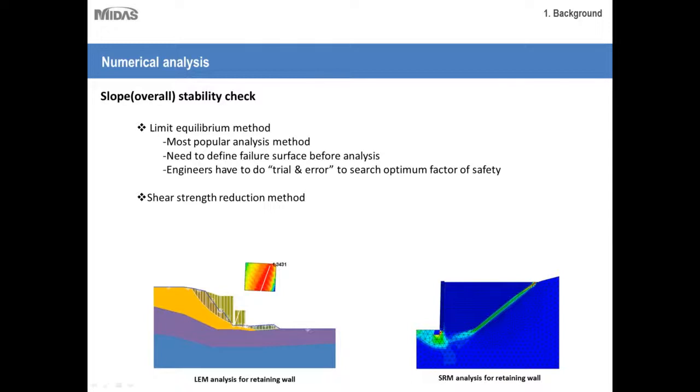Most importantly, here you are not assuming anything. You are not assuming a grid size or doing any kind of permutation and combination. Here the soil is behaving accurately as per the constitutive material model that you have assigned. So it is a more natural and more accurate way of analyzing a given situation.